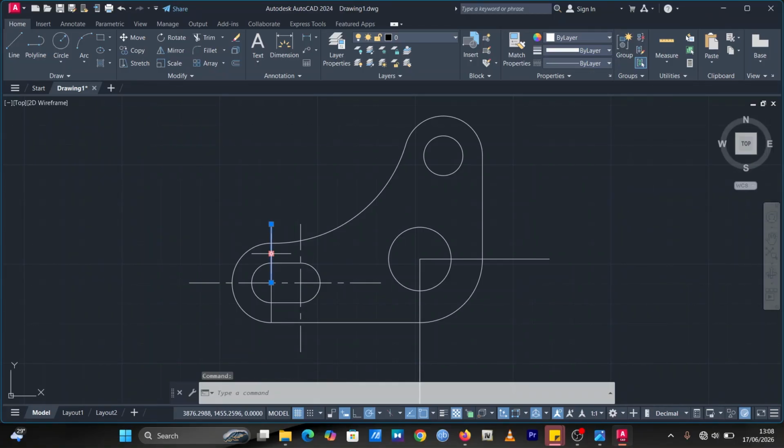Now we pick this straight line over here, we delete it, you pick this one again, you delete it, and then you pick your line tool. So when you pick your line tool, we find the center, which is here. Then we hover around, making sure the green line shows the line is straight. You click, and then you drag it down to pass through the line, and then you click again. Now we have our center lines for this area. You do the same thing for this part too to draw your center line. So let's do that.